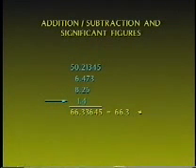In survey computations, it is important that calculations be consistent with measured values. Again, we do not want to indicate false accuracies in our answers. In the addition problem shown here, the answer must be rounded to the rightmost column that has significant figures for all the values being added. In other words, the 4 in the value 1.4. The answer must be rounded to the 10th place, since this is the rightmost column that has a significant figure for each value being added.